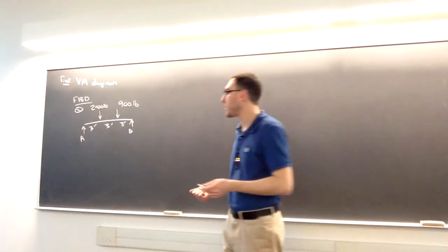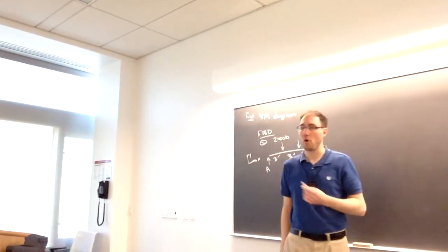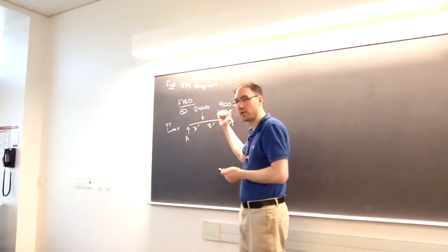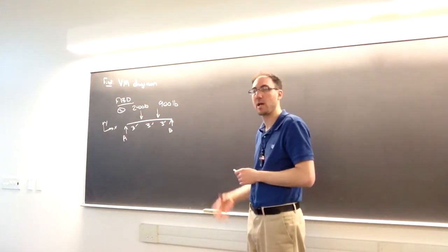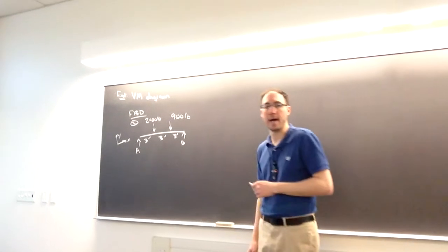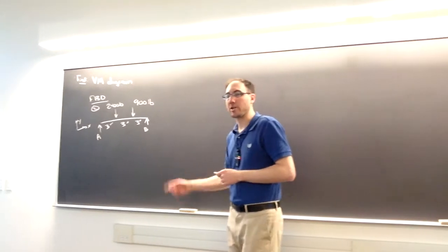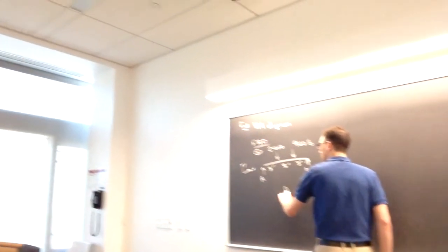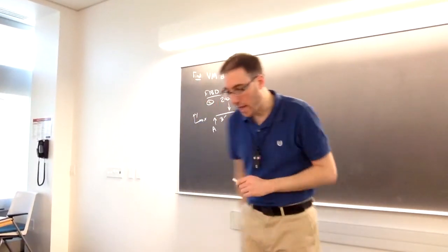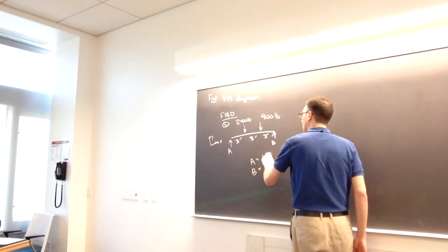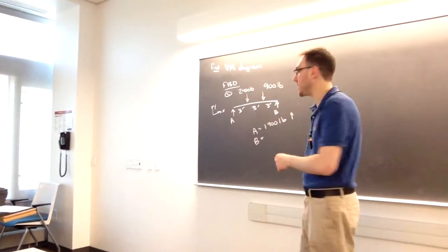Again, for these problems, I can ignore what's happening in what I'm calling the x direction, because these problems feature no internal normal forces along the length. So AX would be 0 anyway. So I'm just concerned about the vertical reactions and couples from my external connections here. All right, so solving forces in the y direction, solving moments around a point, I can solve for the external reactions A and B. A being 1,900 pounds up, and B being 1,400 pounds up as well.